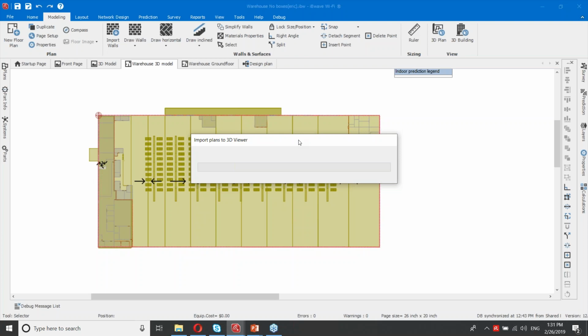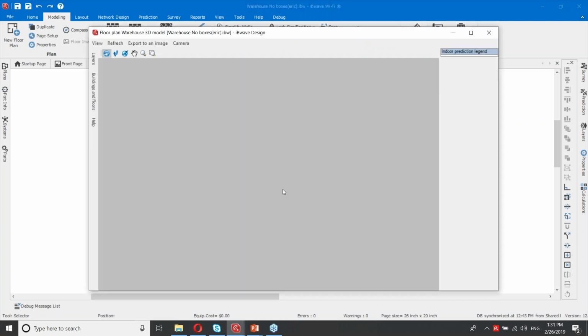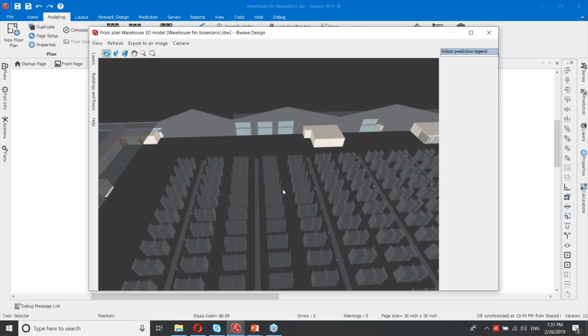Now that really is different than when you have a voice application, where your signal-to-noise ratio should be at least 25 dB. For these applications, when it is low data rate, then 18 dB is enough. And again, if it just so happens that you do not have much noise, then your voice should be -67 dBm, and your IoT should be on the order of -73 dBm.